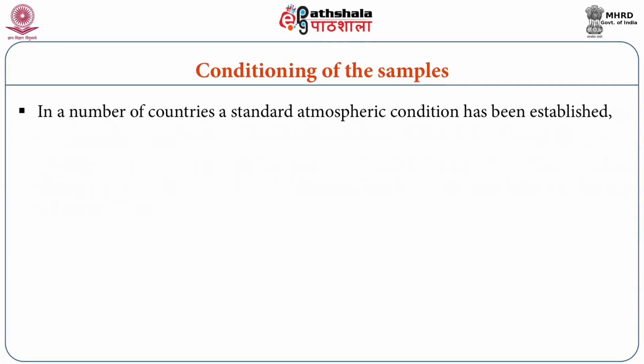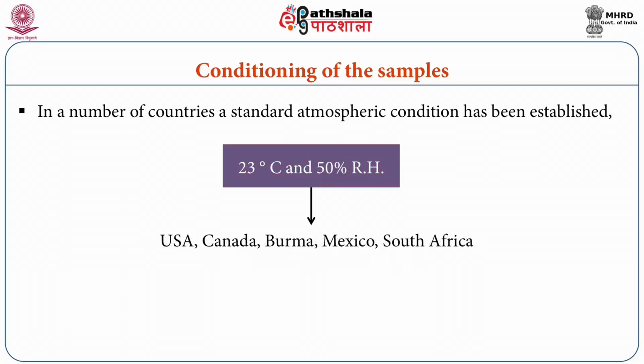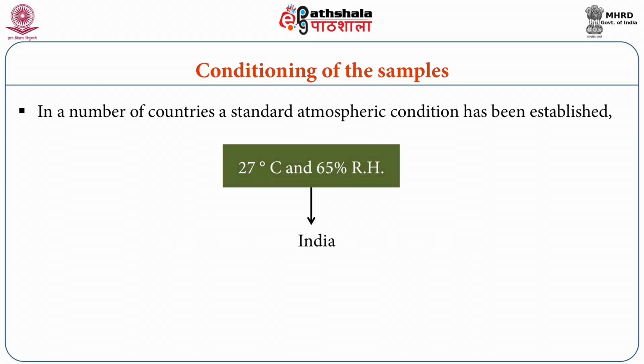In a number of countries, standard atmospheric conditions have been established: 20 degrees centigrade and 65% RH in Argentina, Australia, Belgium, France, Germany, Netherlands, New Zealand and United Kingdom, whereas 23 degrees centigrade and 50% RH in USA, Canada, Burma, Mexico, South Africa. In India the prevailing standards are 27 degrees centigrade and 65% RH.